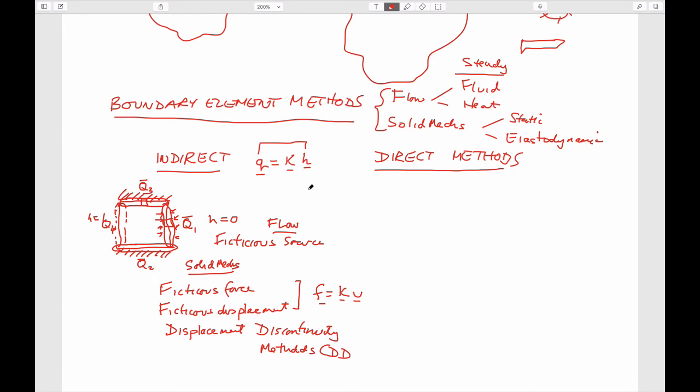We've always thought of elements as being individual triangles or something, but what if, for instance, the element was this whole geometric body? And so the idea is that what we could do is we could apply a force in an infinite medium. So in other words, we could take a force and we could apply that force at a point, and that force would give us an induced force at some other location and also an induced displacement.